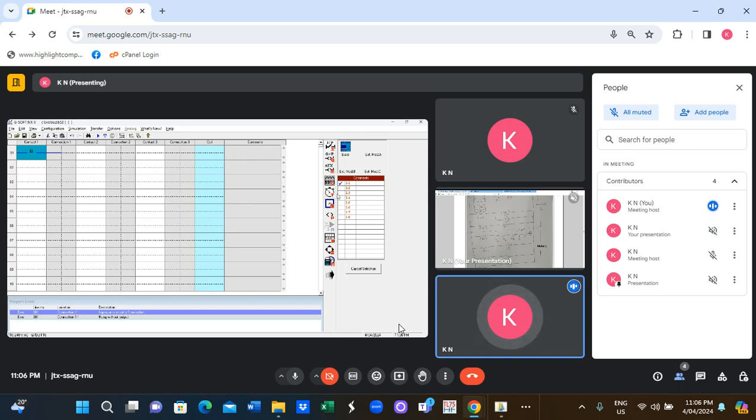Then I also put the I2. I2 is the stop switch. I2 comes in, I put it here. So I also add the I2 contact, and I will put it as normally closed. Now I put I1 as normally open and I2 as normally closed. In this case, click the right mouse button and we put the normally closed. I2 is a small letter for normally closed; normally open is a capital letter.